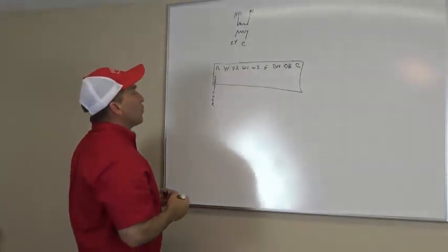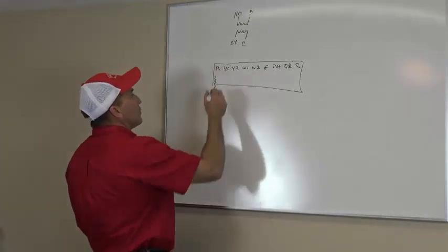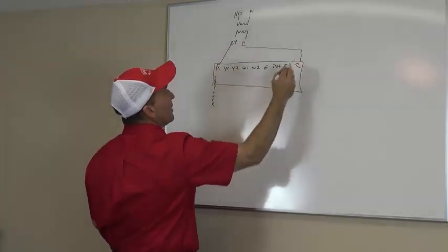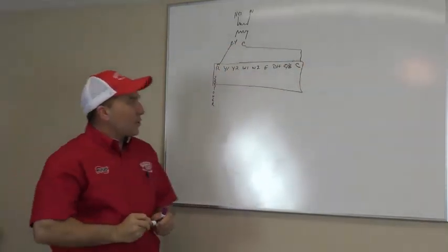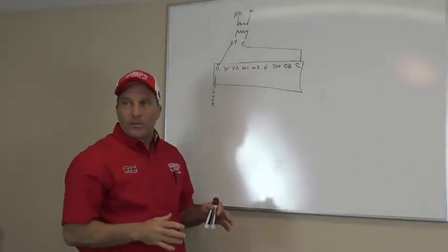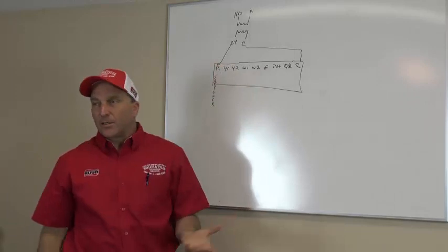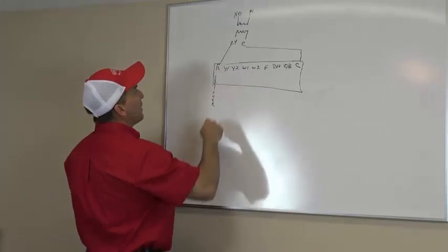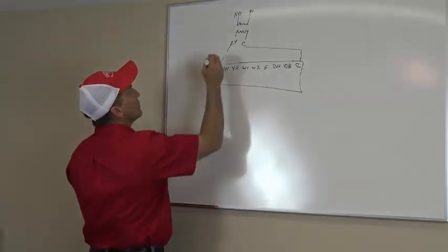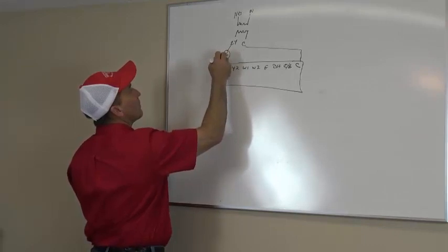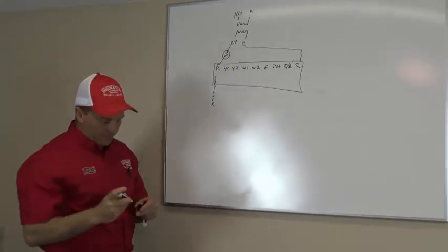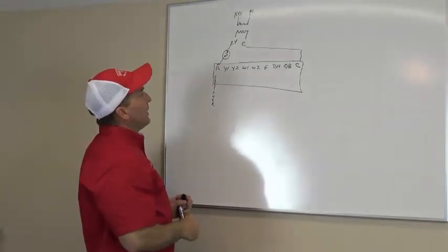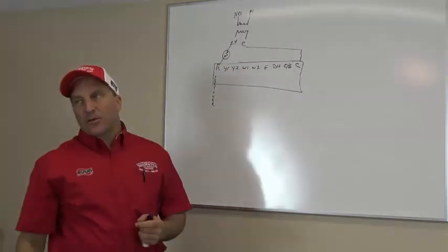If I'm reading 24 volts, where do I read 24 volts to? My 24 volts comes to my R and then goes to my C, right? Okay. From my circuit board, now I'm bringing voltage from my circuit board, because you've got to remember your transformer is right next to your circuit board, right? So voltage is going in there for that, right? What are you going to have in between here, guys? A fuse, right? A fusible link. Okay? So now, if something shorts out, it blows my fuse and not my transformer, right?